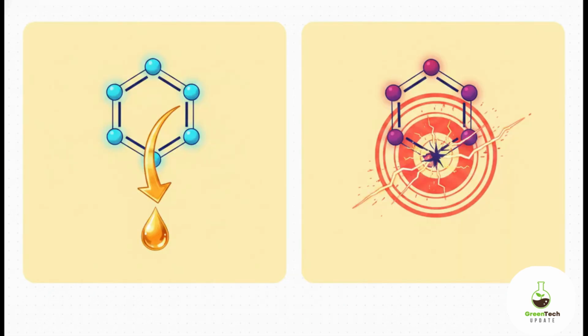Here's a tiny chemical detail that has a massive impact on your final product. Hemicellulose is primarily made of a pentose sugar called xylose. Because xylose lacks a hydroxyl group at its fifth carbon, it physically cannot undergo the dehydration needed to form anhydrous sugars like levoglucosan. Cellulose, being a hexose sugar, can. That one tiny structural difference completely changes your liquid bio-oil composition based on what you feed into the system.